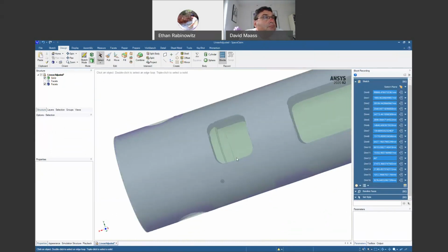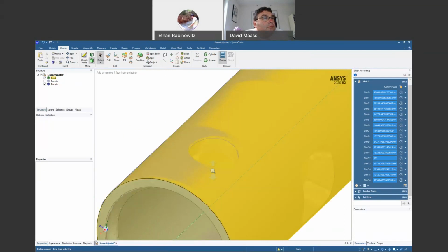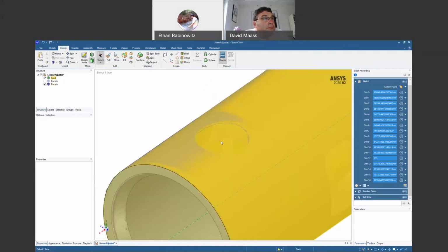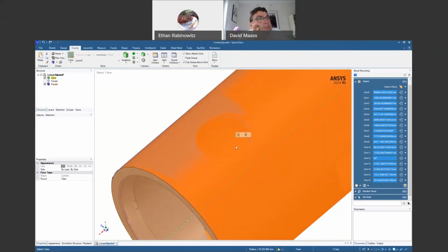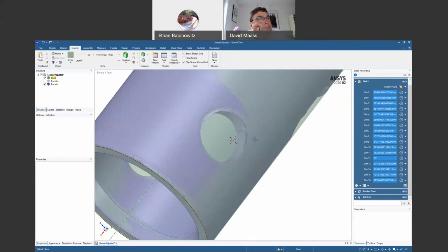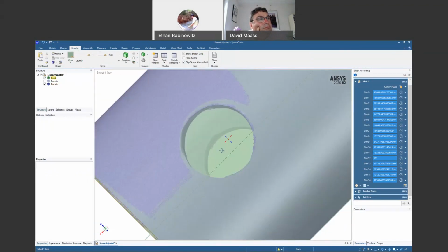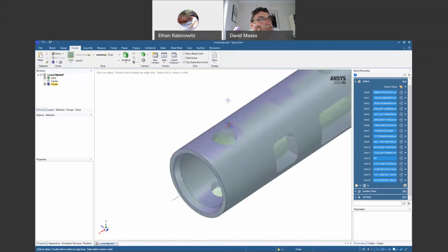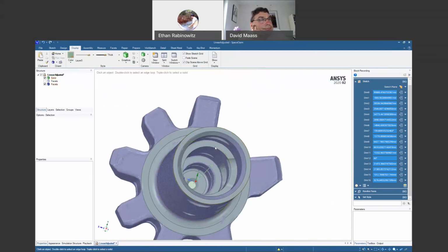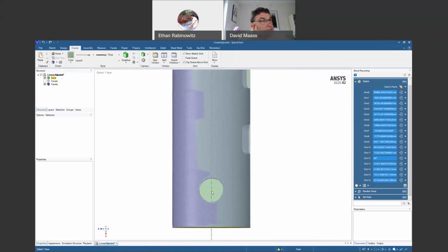I can see that this cutout here goes through a couple different steps, which is fine. Here we have a couple holes. Also, one thing that'll make this easier to see, because I don't want it to highlight the face, in the display tab, you can control what's shown, and that includes the face highlight. So now I can actually hover over the model. I can still select things, and that's when it illuminates, but now I can hover over and not get really bright in our face here. So looking at the holes, I'm going to make an assumption that we just want one perfectly cylindrical through hole that goes through both of these at the same time. Looks like it's going right through the center, and nothing too different or complex about it.